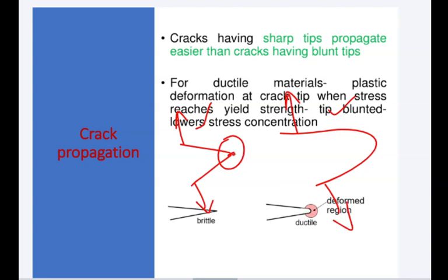Only this corner, you see, very little material, very little area is exposed to the deformation. So once you apply the stress, suddenly it will break, because the whole force, the total stress, is concentrated at this point. While if you see here, in this image, the stress is not concentrated at one point. It is on the whole region.